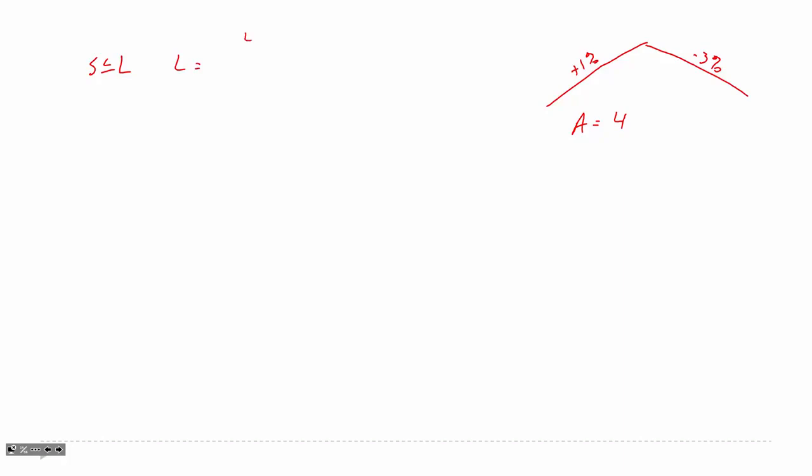So we get 4. We were told that our stopping sight distance is 1,000. So 4 times 1,000 squared divided by 100 times the square root of 2 times H1, which was 4 feet, plus the square root of 2 times H2. H2 is 6 inches, so that'd be a half a foot. Those units have to be the same. And then everything there squared. So solve for that.